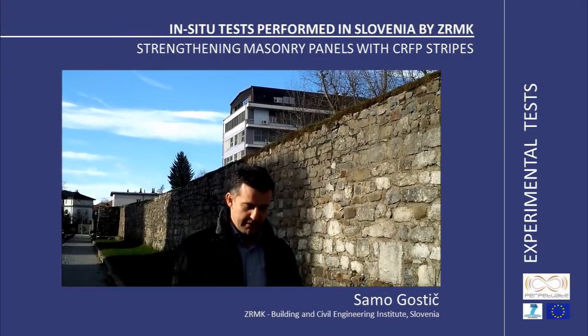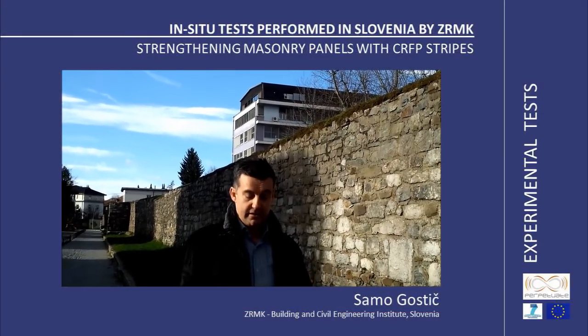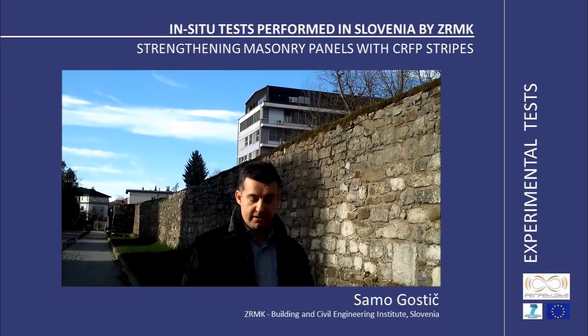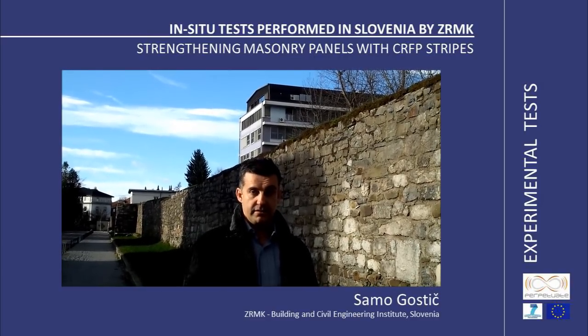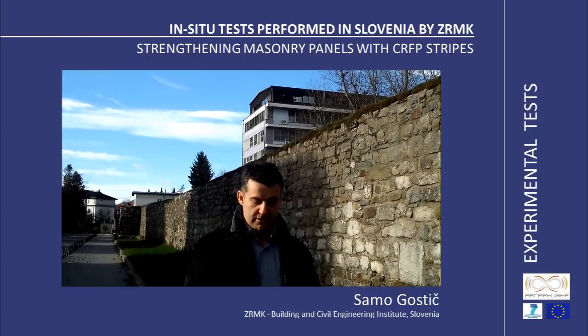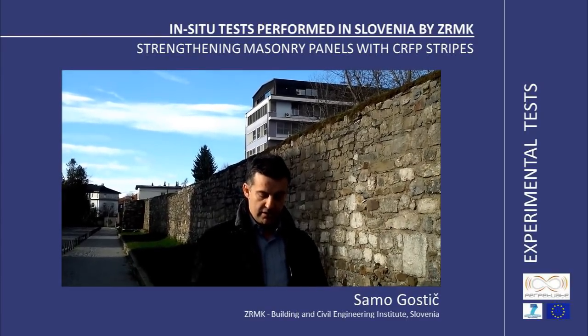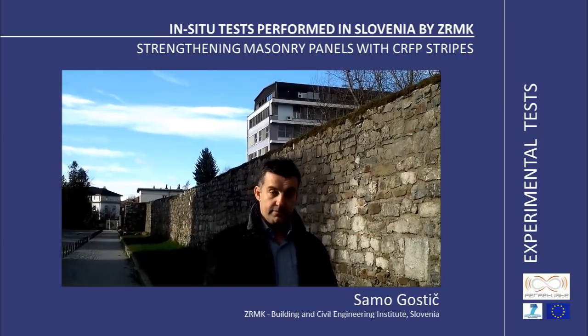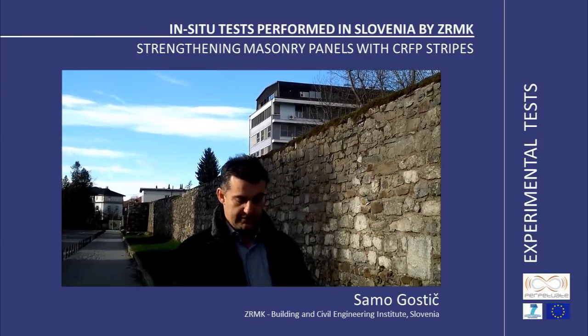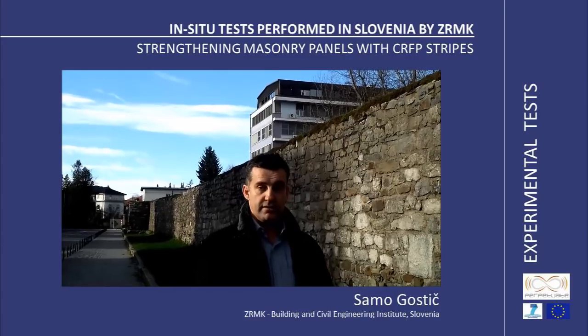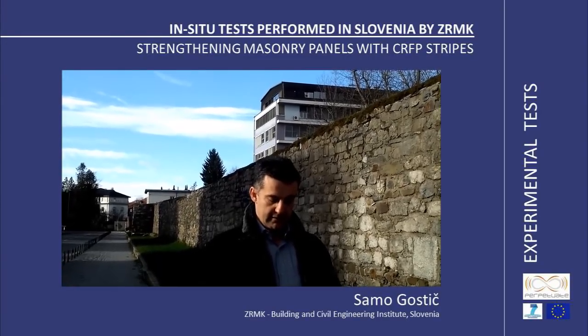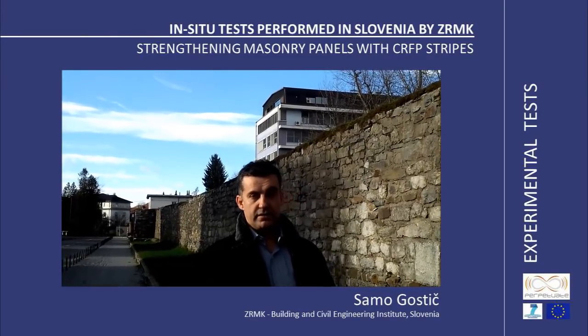Results of experimental tests are very important to gather real information about load-bearing element strength and deformation capacity. That is vital for realistic structural analysis, and on the basis of experimental results the safety factors can be lower, and so less intrusive strengthening techniques could be used.